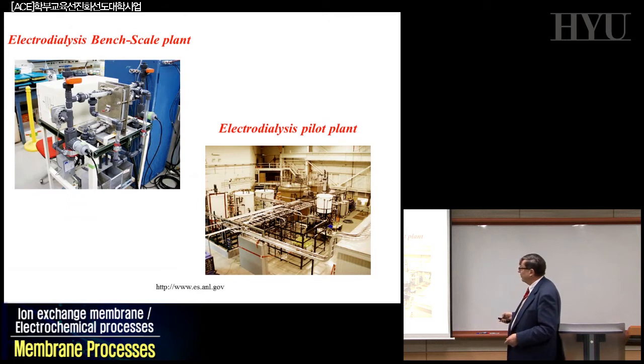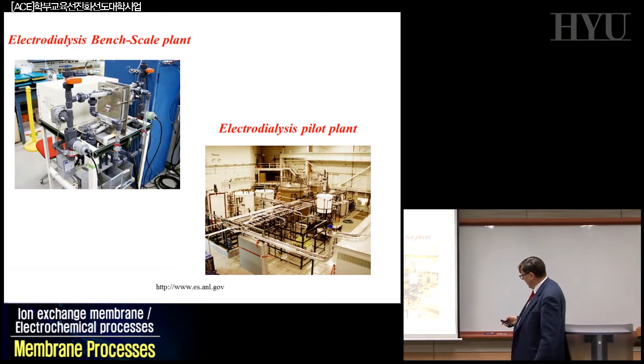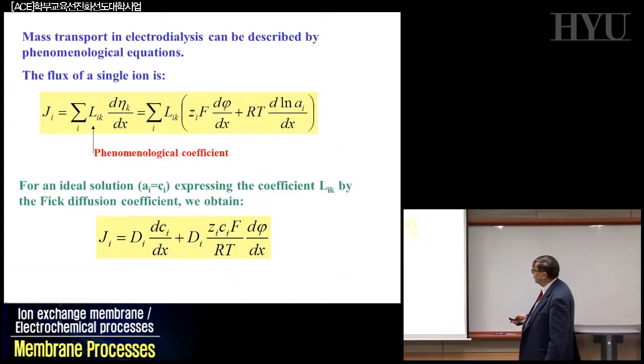As in reverse osmosis, you can realize thousands and thousands of these single cells packed together, and that is, for example, I think, in the dairy industry, and this is a cell in the lab. Also in this case, you see these units, but between these cathodic and anodic compartments there will be at least 30, 40 different cells packed together, with the anionic and cationic membranes in between and the spacers. That can be multiplied and become huge, as we discussed in reverse osmosis.